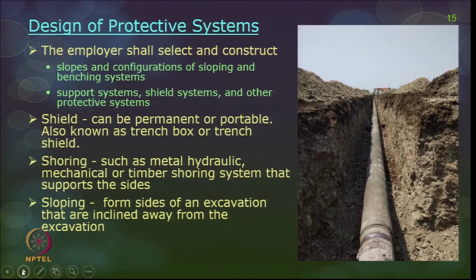Whenever you are cutting out the earth, a lot of protection systems are available, and number one is shields, then shoring and sloping. So, shielding, shoring and sloping are the three methods of protecting any open pits or trenches and so on. This picture is primarily to show that the excavated material is lying far away from your cut portion, and you can see this pipe laying operation, and the excavated earth is not piled up all along the walls but a little away from the walls.